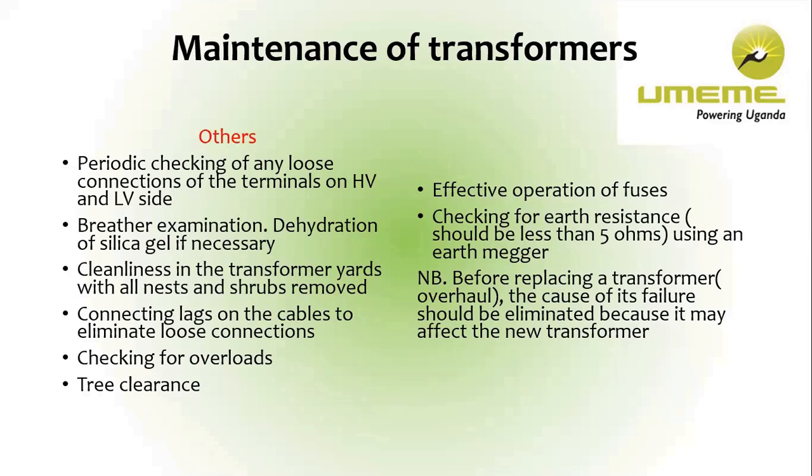So when you go to check on the silica gel and you find it pinkish, or if you find it has changed color, you overhaul or you dehydrate. So Joseph, that's what we check on the breather examination.